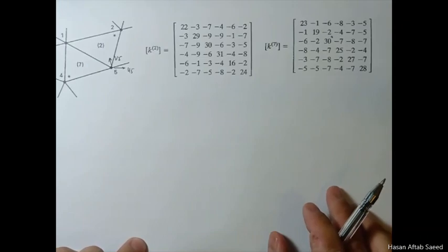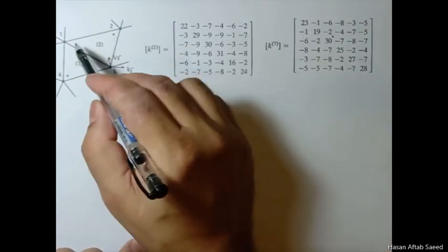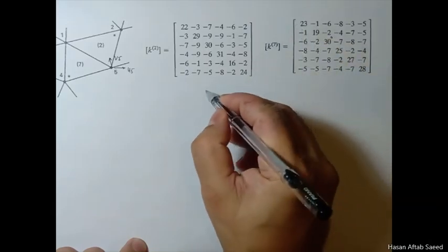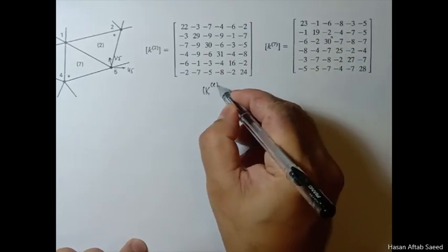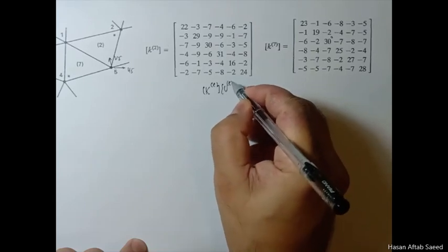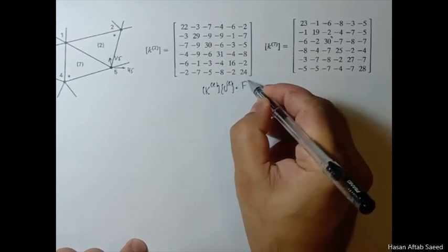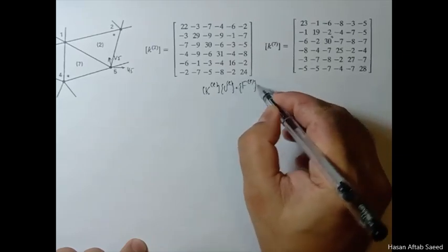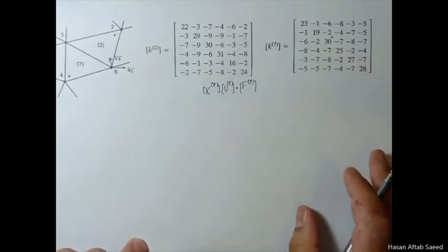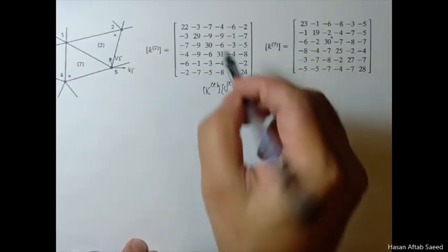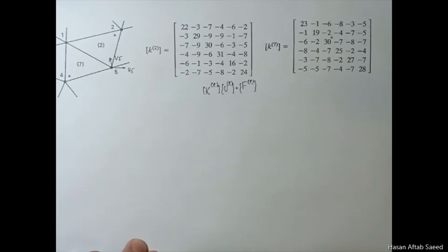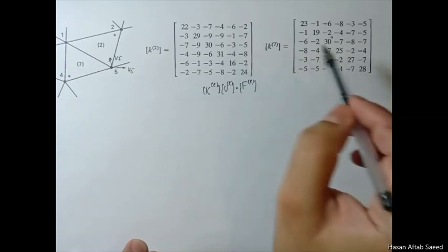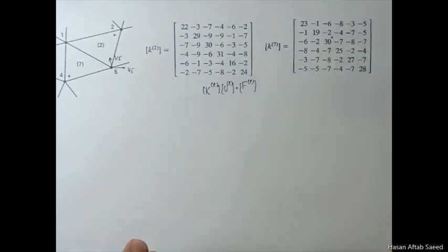So there are 6 degrees of freedom per element, and then you have your U as well as your F matrix. And what I'm talking about here is this. If this is 6 into 1 and this is also 6 into 1, then this has to be 6 into 6. So it makes sense. We are talking about stress analysis problems. Now, for 3D systems, obviously the size will be much bigger. Otherwise, what we are going to learn today holds for 2D, 1D, 3D, every kind of system.